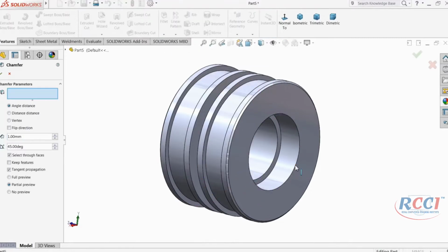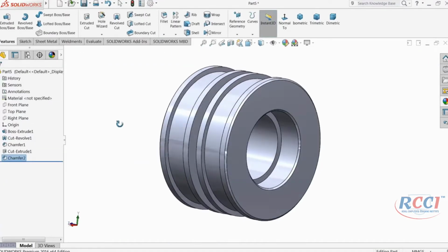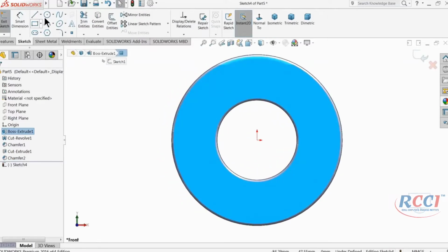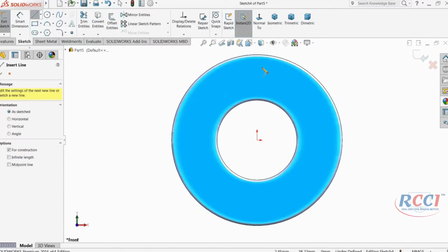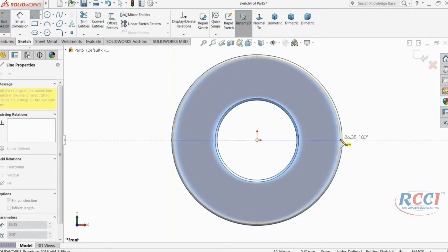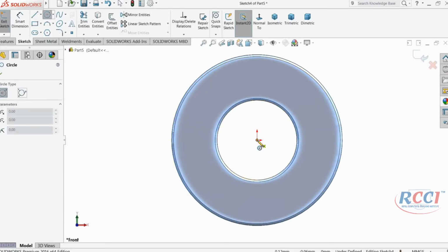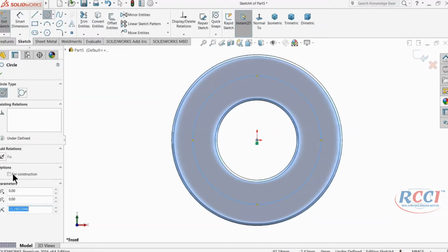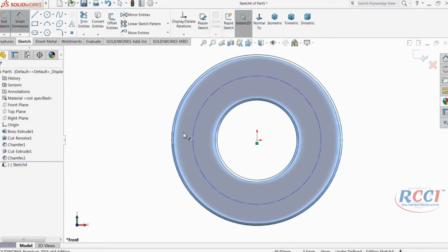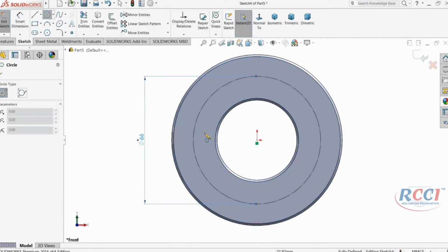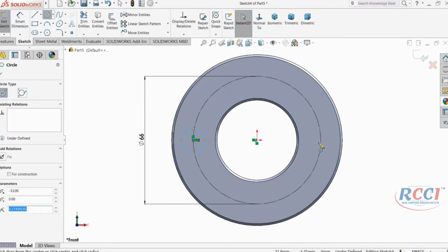Make chamfer 1 millimeter and select this corner. Select this face, sketch normal, and here we will make some... or do one thing, circle, and let's draw a circle up to mid for construction. Okay, let's choose it, 66 millimeter circle, and here draw two circles, exit.